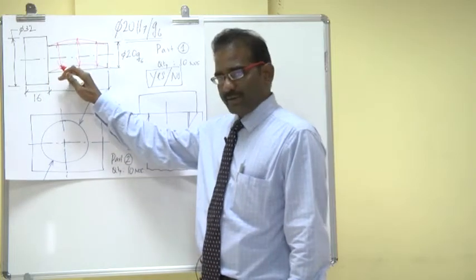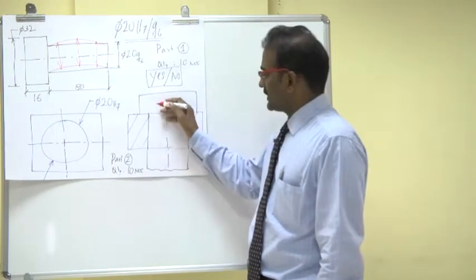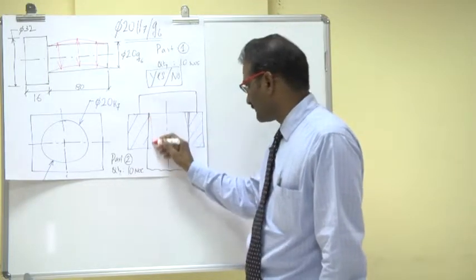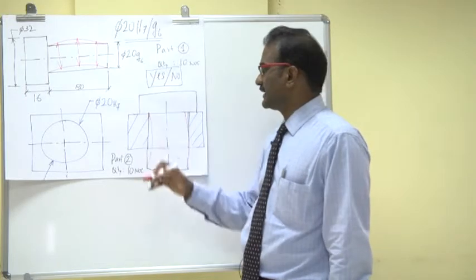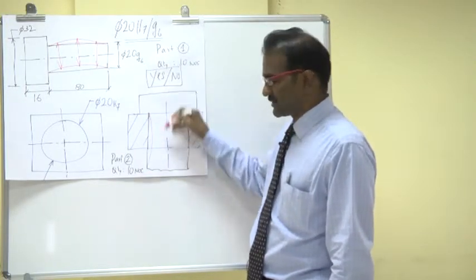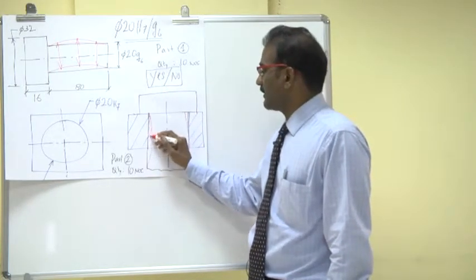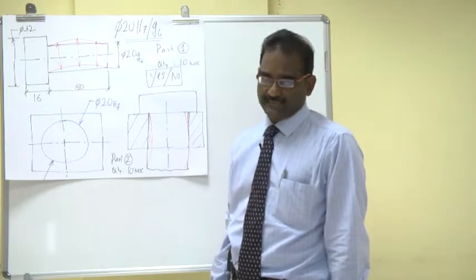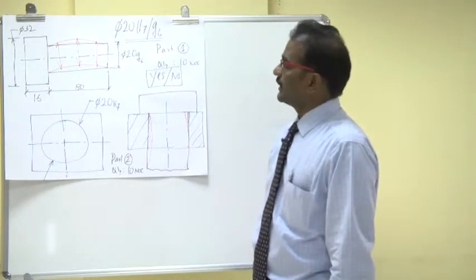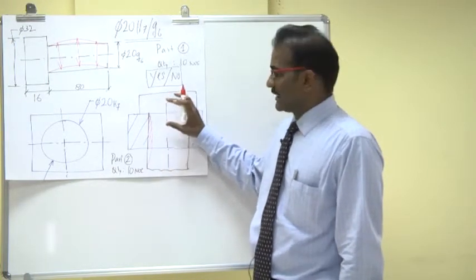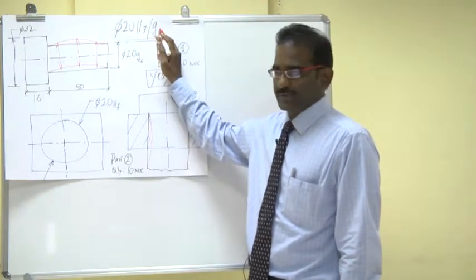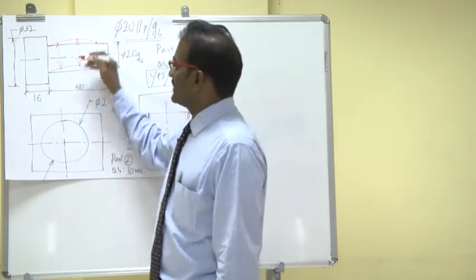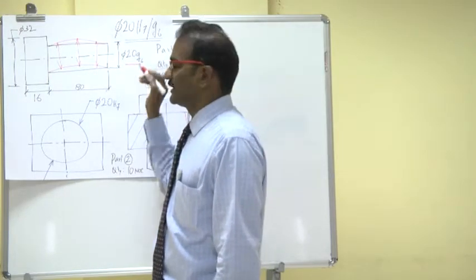However, because of the bend, I may get into a situation where the shaft will not enter the hole at all if the bend is too much, or if the extent of bend is within limits, I can realize a situation where the shaft is entering inside the hole, but the degree of clearance all along the periphery is not uniform as intended by my design requirements. So that's why, in order to ensure the design requirement of having H7 G6 fit in the assembly, I need to control the form error or shape error in addition to maintaining the size within limits.